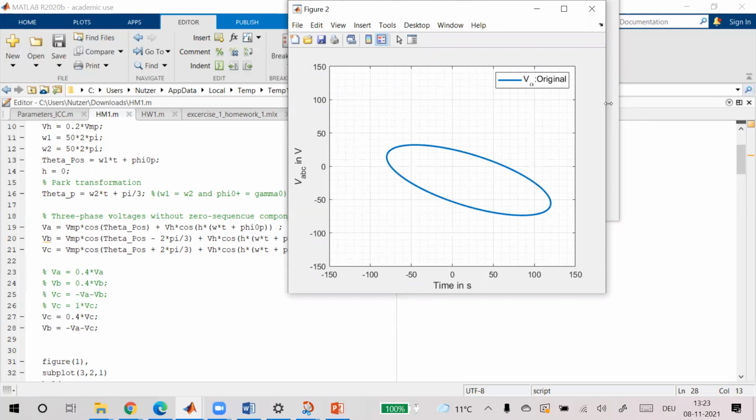Okay. So whether you may have 0 sequence or may not have 0 sequence, we would see a similar shape. So we probably will not bother you much about the magnitude, because this magnitude changes when we do a fault with some voltage, but maybe we can give you the shape and then ask you which fault it is. So you also have to see whether it is symmetrical or unsymmetrical, and which phase it is. Okay.